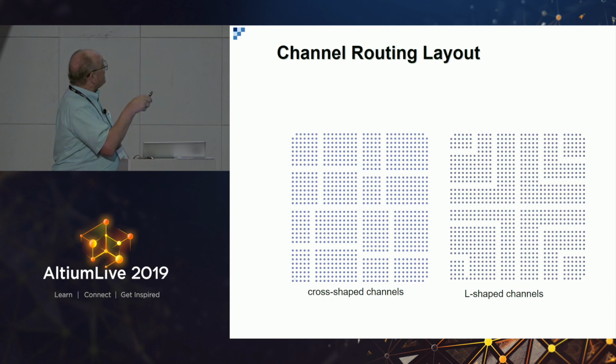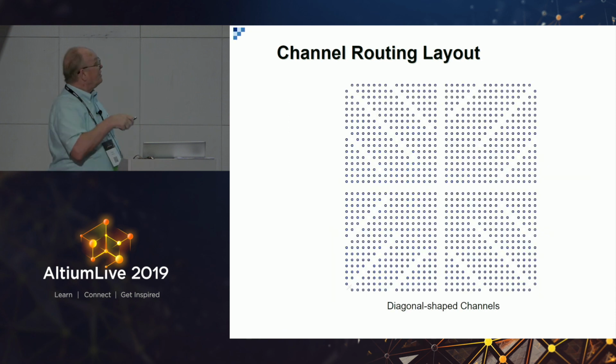And so they can be cross-shaped, they can be L-shaped, or they can be diagonal, depending on how the IC people have situated either their power or their ground in terms of geometry. Once you figure out that pattern, that's the first place to put the blind vias, because now you have methods of signal escapes inside the PC board, because where the blind vias are on the surface, underneath them that's open now for routing and more escapes, which you can't do on a through hole system. The hole goes all the way through the board, but the blind via doesn't.